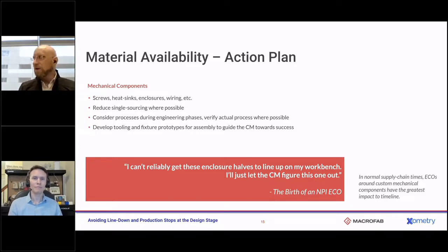Yeah, and to build on that, we have used 3D printed variants of designs to test fit in processes before. Because one of the big challenges we see, like in alternates, is we'll do something like, say, a big electrolytic capacitor, right? Your alternates actually have two different heights, but you never think about that as a design engineer because you're focused on the primary one. All of a sudden, we build with that new alternate with that second height, and it doesn't fit in the enclosure, right? The whole product doesn't go together, or wire needs to be rewired. Flashbacks. We see that a lot, and like Greg's point, our first article assembly facility has an entire array of 3D printers to create things to fix problems in the process instantaneously, just for that reason.